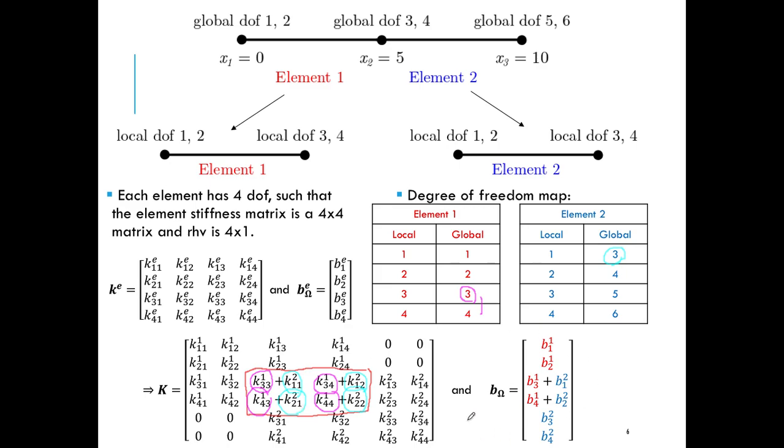इसी तरह हमने अपने body vector को भी या फिर domain vector को भी which contains the effect of the distributed load, उसको भी इसी तरह assemble करना है using the local to global degree of freedom map, noting again कि it's only the 3 4 degree of freedom जिस पे वो दोनों elements contribute कर रहे हैं.